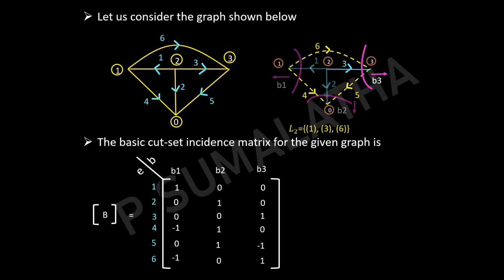Sometimes whenever we are doing numericals, we need to consider the basic cut set matrix exclusively with respect to branches, sometimes with respect to links. So we need to partition or split this matrix accordingly. In our graph, the branches are formed by elements 1, 2, 3 and the links are 4, 5, 6. So we separate the branches and links just by drawing a straight line.